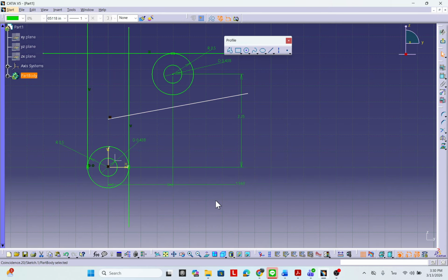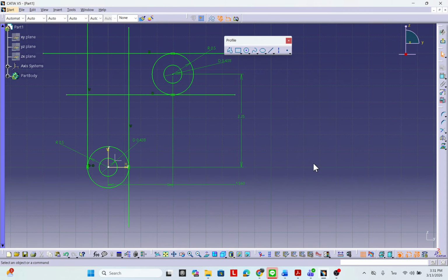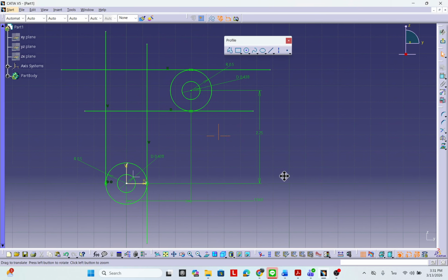Okay, how to solve it? Delete the constraint. Okay, move it. I moved it. Okay, I need to click on here. I get it. It's just only one. I need to make the constraint tangent, right? Okay, and another thing you need to do, you must do this. Okay, horizontal. Right. Okay, I get it, and finish. Nearly finished. You just use it.